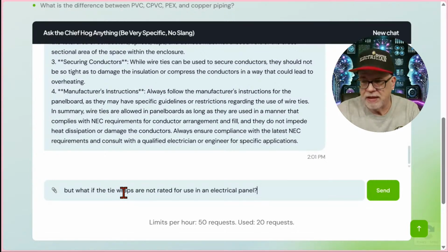One of the issues, for example, with a tie wrap is people say, well, if we put it in a panel, then it's plastic. But very rarely do we get anything on a tie wrap that's listed other than for securing and supporting. And if it's being used as a securing and supporting component, then it's being used in compliance with its listing, if it is listed. So whether I use them in a panel, I don't think I would have any heartburn over it personally.